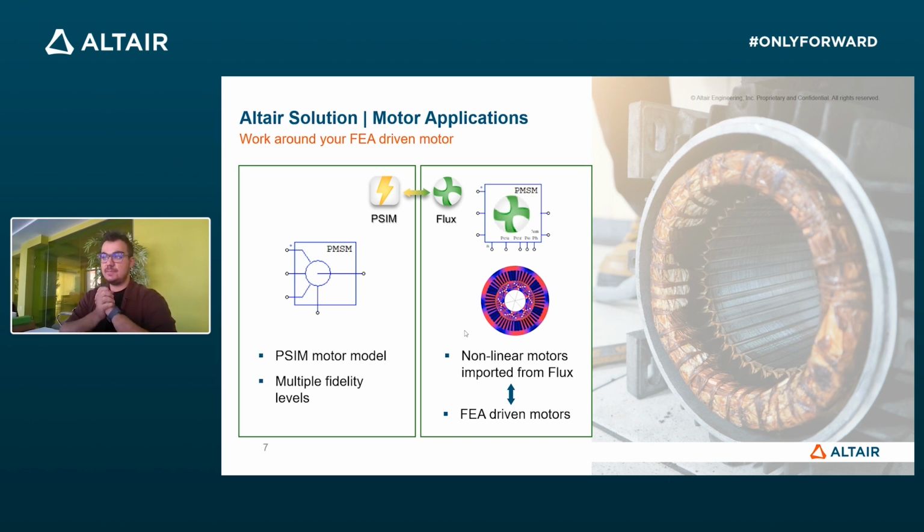So Letizia talked about Flux, and essentially you can design your own motor inside Flux or FluxMotor. This will be, of course, a geometry-based model, and you can export that as a lookup table and import that into the dedicated FluxMotor model inside PSIM.